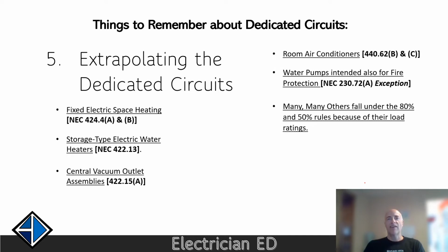However, here's the exception. If there's a water pump on its own feeder line from the metering equipment with its own dedicated overcurrent protection device, it can be used as one of the 2 to 6 disconnects, even though it's not grouped with the others. But it has to be an individual branch circuit. So also, I might as well note this.